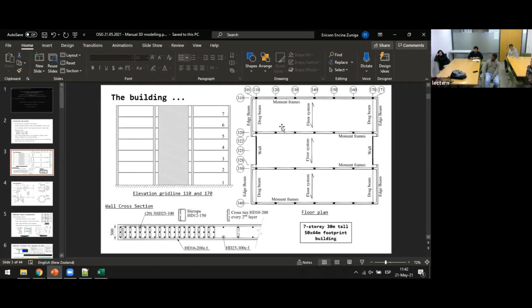Since you're given a distributed load, you just grab that area times that load, and then the procedure assigns that load to the node. Then it does the same thing with the one that is beside, beside, and beside. That's the way the nodes are all loaded with whatever load you want.